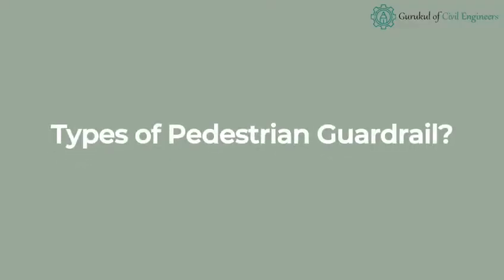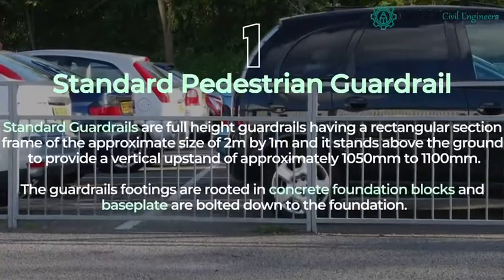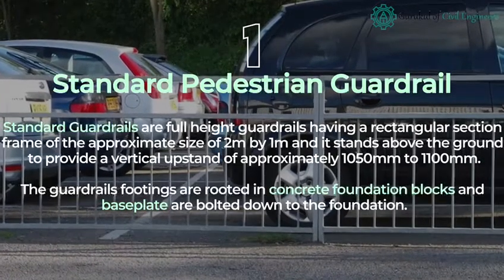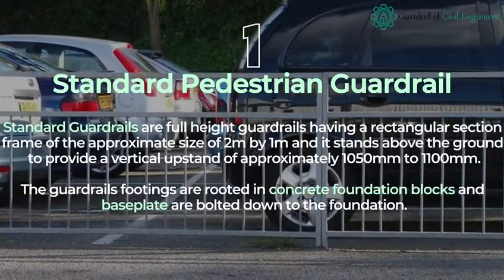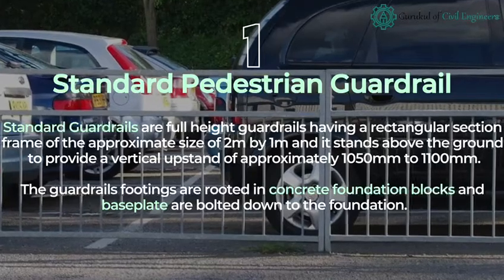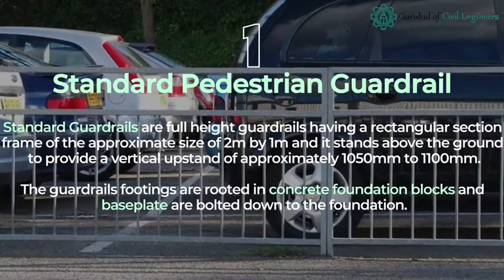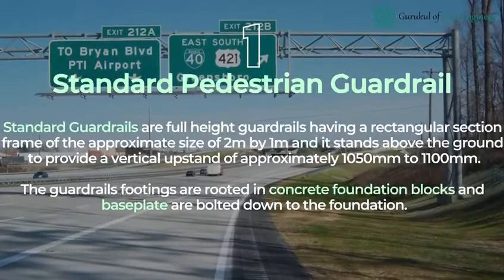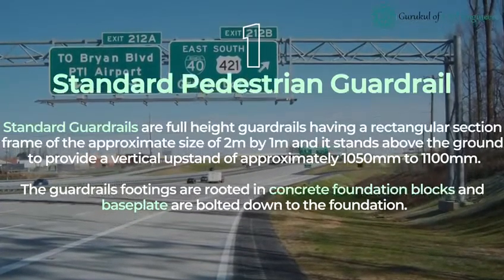Types of pedestrian guardrail. Standard guardrails are full-height guardrails having a rectangular section frame of the approximate size of 2 meters by 1 meter, and it stands above the ground to provide a vertical upstand of approximately 1050 mm to 1100 mm. The guardrail's footings are rooted in concrete foundation blocks and base plates are bolted down to the foundation.